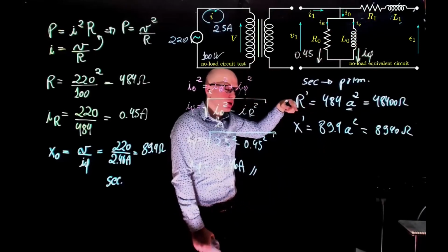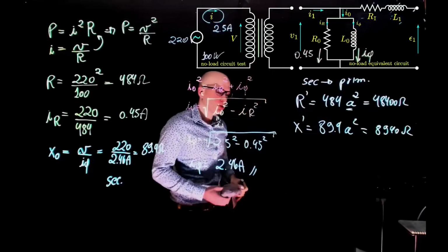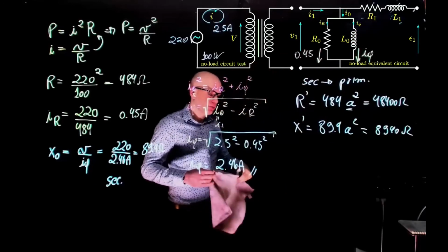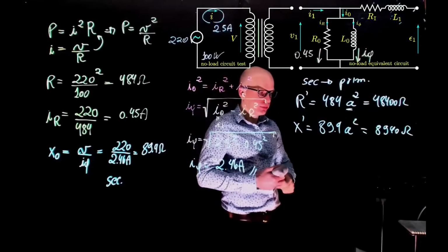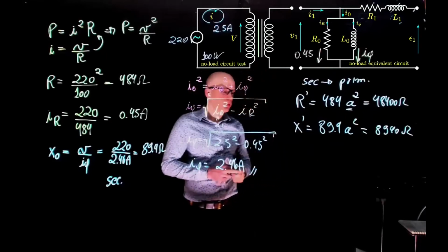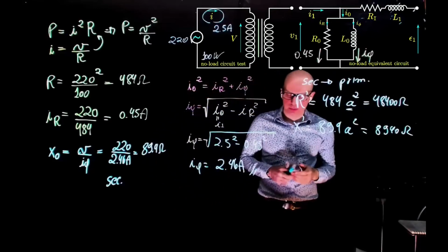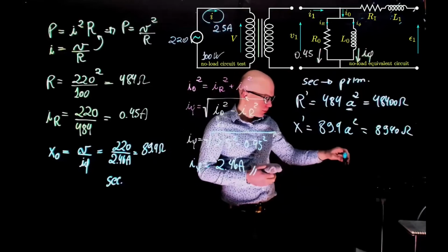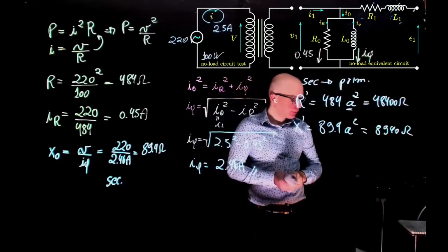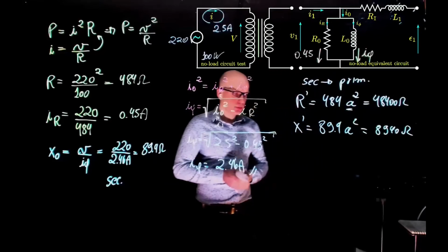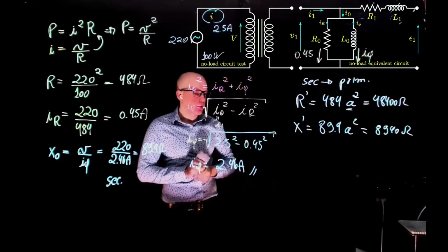If we add an impedance in the secondary, then the current would flow there, and most of it would have to be recalculated. Right, and that's why we said I1 equals I0. Okay, now everything makes sense. And we used V2 in our calculations. We used 220 instead of 2,200 because in this test we're treating the secondary winding as a primary winding. Exactly.